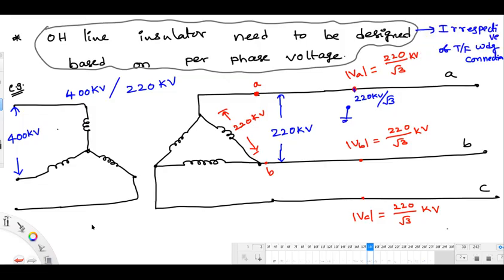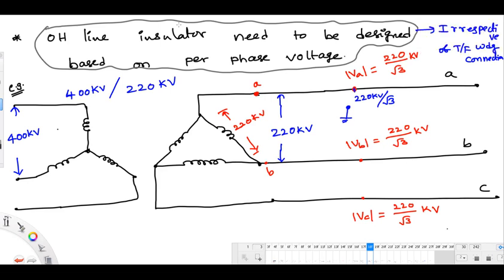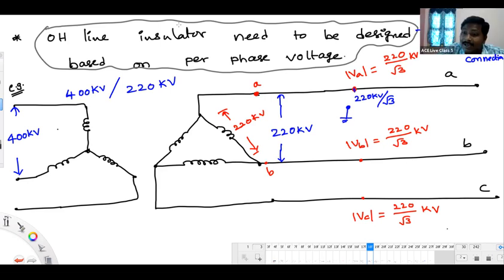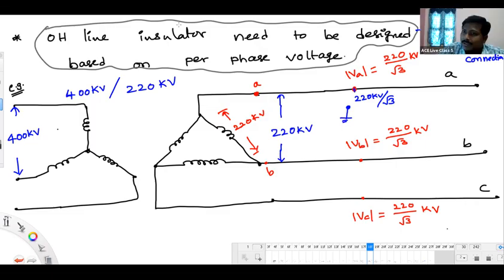Naveen, whether you are opening the breaker or closing the breaker, whatever it is, you are disturbing the position of inductor and capacitor charging. Whenever you disturb the charging position of inductor and capacitor, definitely there will be a transient creation. Definitely it may lead to an over voltage sometimes.